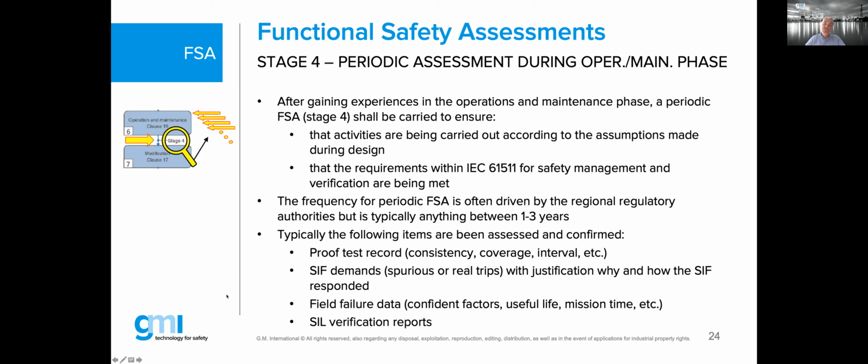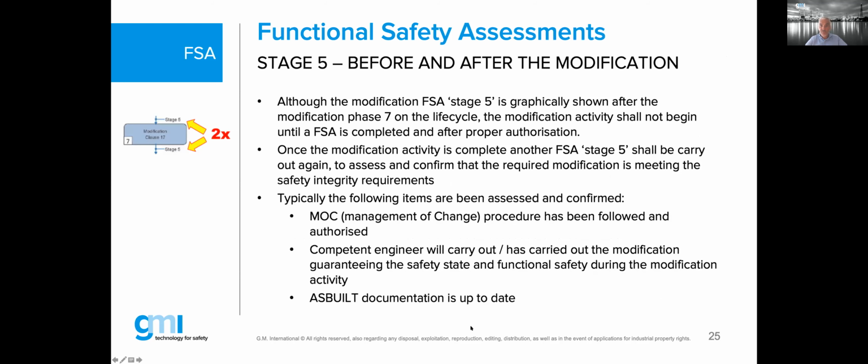And last but not least, of course, we want to see your SIL verification reports. We want to see how you come to that decision. And of course, that will all be linked to your failure data and to your proof test coverage / interval / consistency, etc., etc. One more slide to go, stage 5.